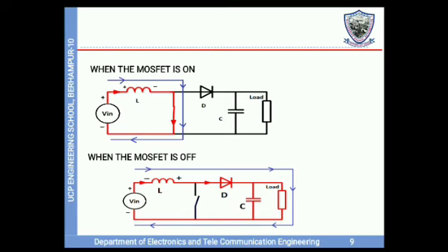The higher voltage passes through the diode and charges our output capacitor. The diode prevents the charge flowing backward and ensures the stored charge is passed to a load connected to the output. The MOSFET is turned on again before the capacitor loses any significant amount of charge, to maintain a steady voltage across the output.